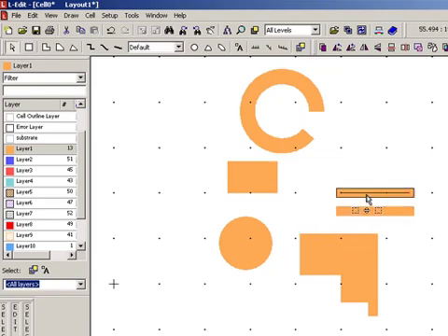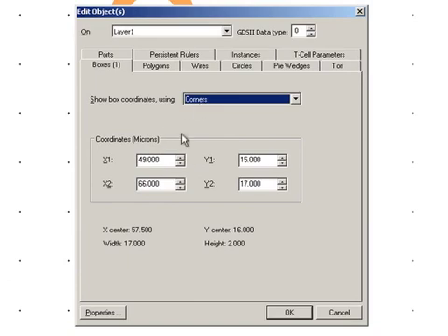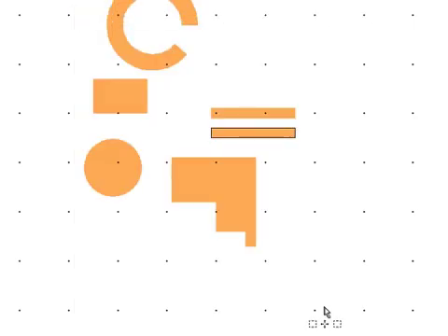Because what happens is if that width parameter doesn't get exported properly, you end up with a feature that only has 2 points and no thickness, so it's really only a one-dimensional feature, and in that case you end up with nothing on your mask. So to be very sure of our geometry, if we select the box here, we'll see that it's defined by 4 corners, and so we're very sure of the width and the height of that box when we export this feature into our final design.